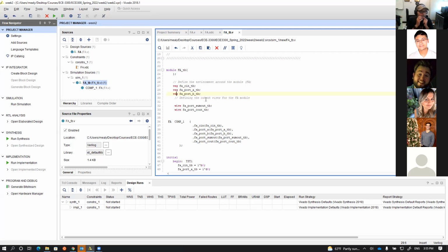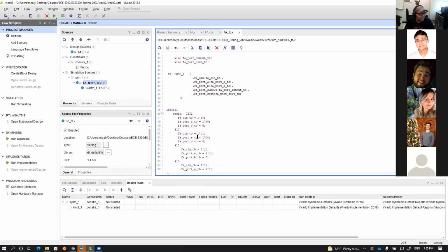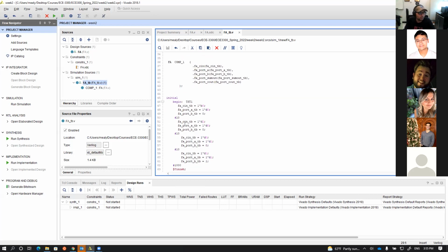Again, in this context, why do I make the inputs registers? Because at the end of the day, I assign values here and keep assigning values over time. It's a kind of storing element, because it changes with time. But in a wire, you cannot do that. The wire just passes. You cannot say that in a wire, after 10 minutes, it will be something else. It's just a wire. I think I get it now. Thank you so much. You're welcome, sir.